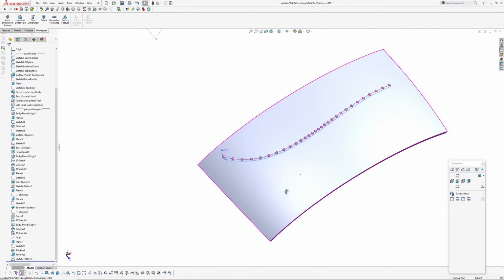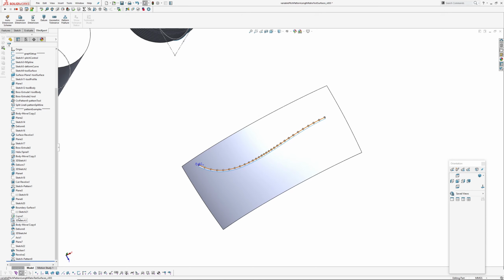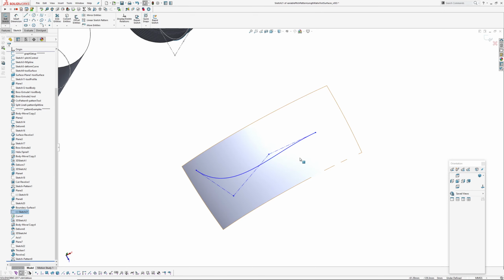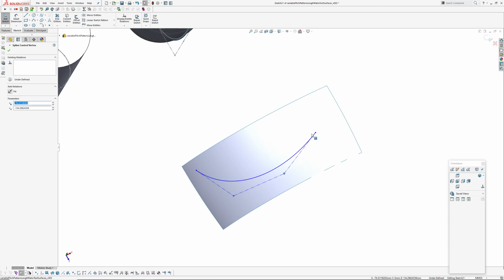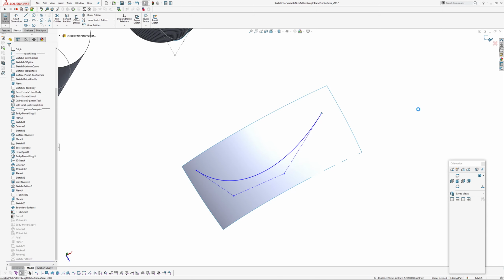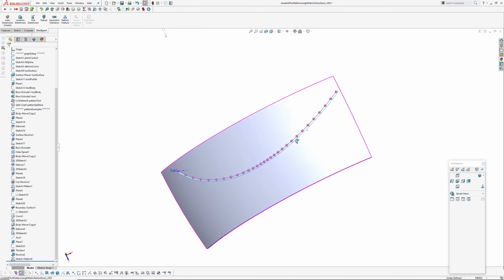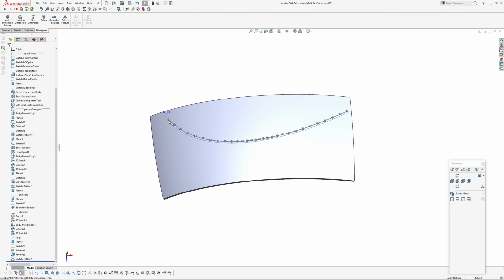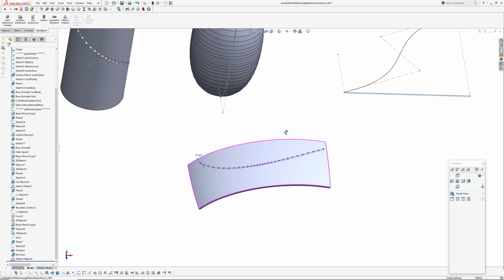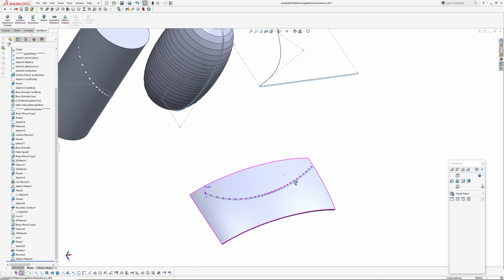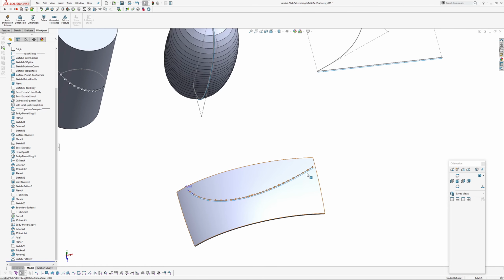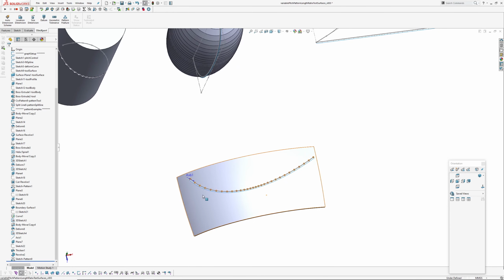And these things update, so if I go in here, where's the projected curve? This curve here, it's getting projected on. I go like that, it will update. Because the 100mm curve is basically going to spread the length of these across whatever length, like a length ratio, across whatever your target curve is. The spacing all happens automatically, which is nice.